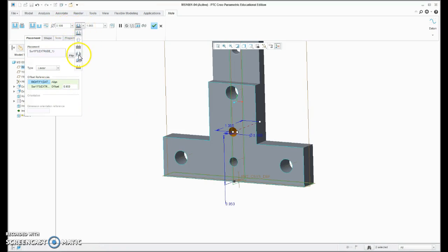So this one as well goes through. This one's got a little thread on it, it appears. So I'm going to go to a threaded hole and make this a 10-24 hole.